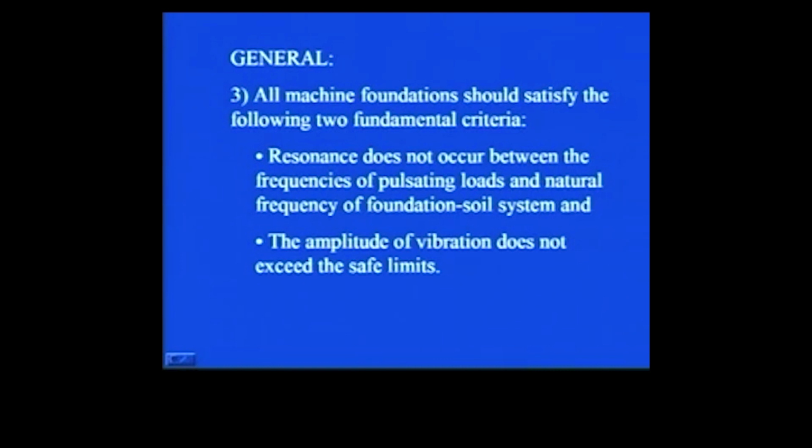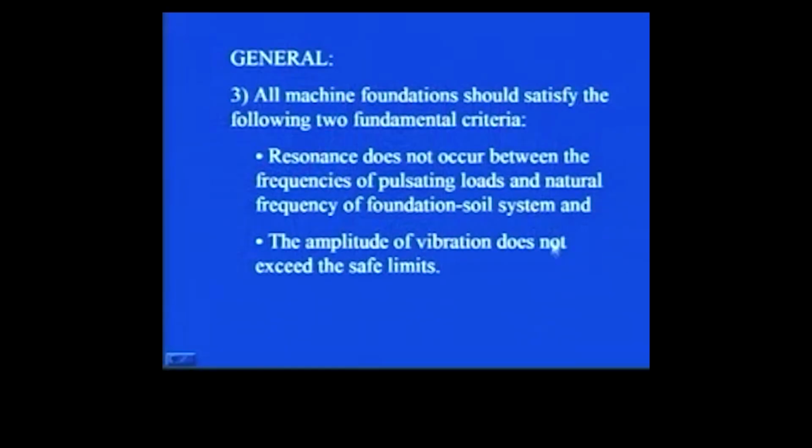One is that resonance does not occur between the frequencies of pulsating loads and the natural frequency of the foundation soil system, because you know that at resonance the amplitude is almost infinite. So, usually we avoid this resonance. This resonance should not at all occur between the frequencies of loads and the natural frequency of the foundation soil system. And the second one is that the amplitude of vibration does not exceed the safe limits.